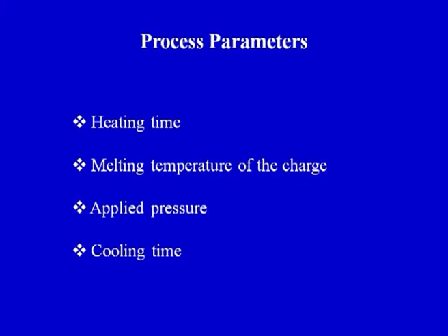The plastic which was under elevated temperature is now slowly coming down to room temperature and getting its final shape. So for how long the two mold halves or the two die halves should remain closed is also very important, and that can be called the cooling time. So the cooling time is also equally important.